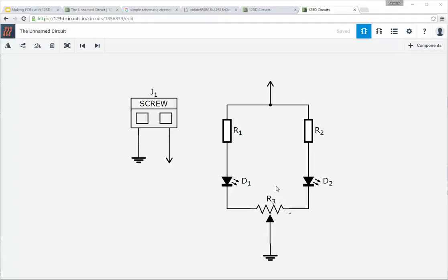Potentiometers are basically just resistors, but they have a knob on it so that you can turn the knob and change the resistance coming on either side. These items have 3 pins, so you can connect to 3 different things. It's connected to one half of the LED circuit, as well as another half of the LED circuit, as well as the ground.